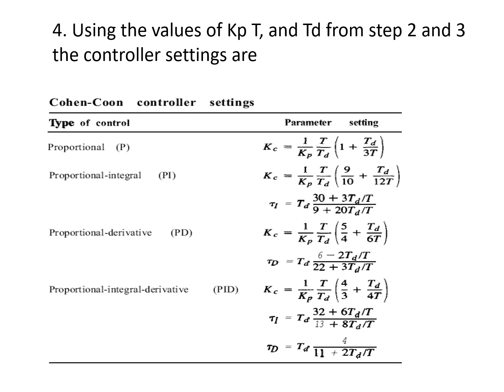Once you have the Kp, T, and TD from step 2 and step 3 just now, you feed them into this controller setting parameter equation that was developed by Cohen-Coon. Again, it came from trial and error through experimentation in the industries, in their instrumentation company, if I'm not mistaken, Foxboro. They did a lot of testing on their systems, and they found, okay, for a P controller, this is the equation you can use to get your Kc value.